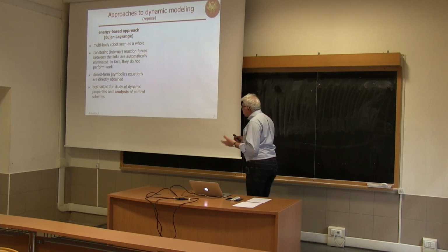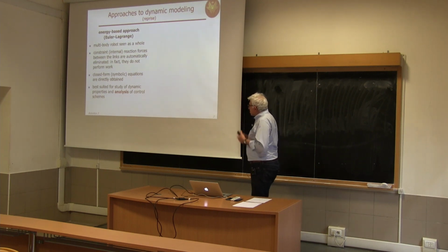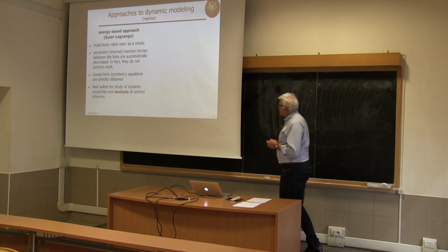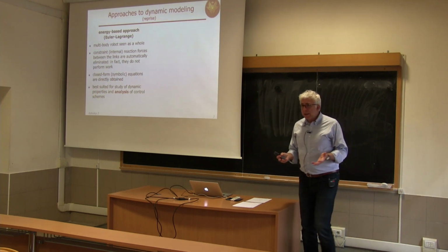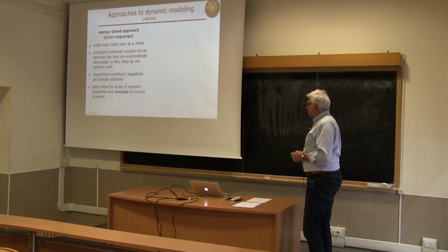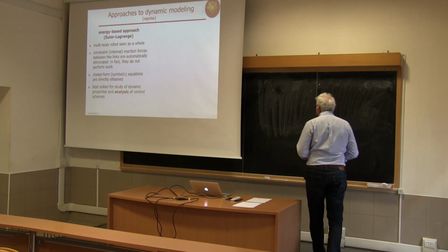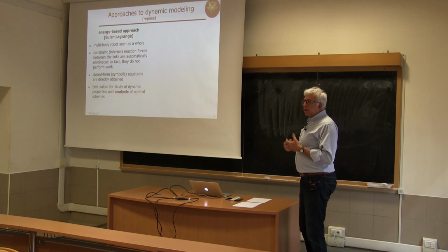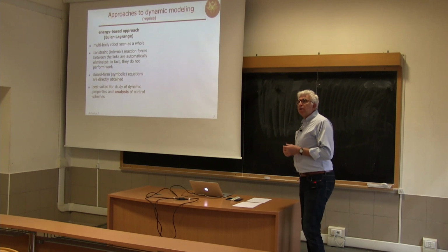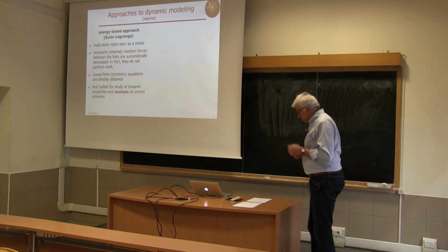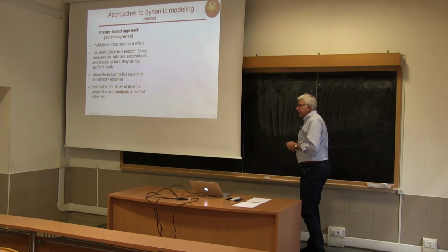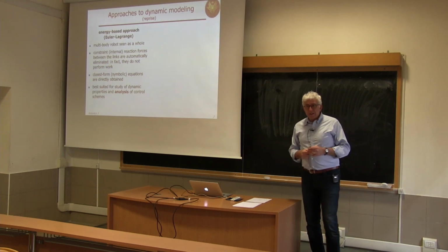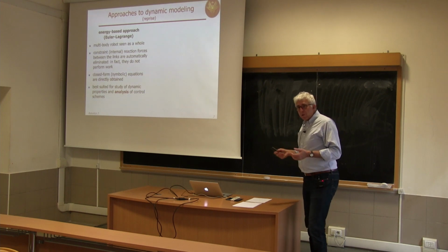We end up with a so-called closed form equation, expressed in possibly long symbolic terms, which completes in one shot the dynamic description. Now, apart from detailing the single expression of the dynamic terms, the general structure that we obtain from the Euler-Lagrange approach allows us to study some generic properties of the robot. For instance, we have seen as a first and basic property that the inertia matrix is always a positive definite symmetric matrix, and therefore it can always be inverted.